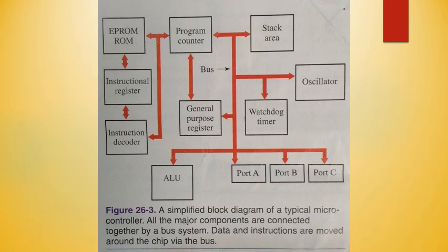Ports and registers. There are many different types of registers and ports found inside of the microcontroller chips. Ports and registers are special memory locations dedicated to a specific function, such as a hardware location or place to manipulate data. Some ports correspond to the input and output pin assignments of the chip. By placing a 1 or 0 into a specific port address, you can change the pin assignment of the microcontroller from an input pin to an output pin.